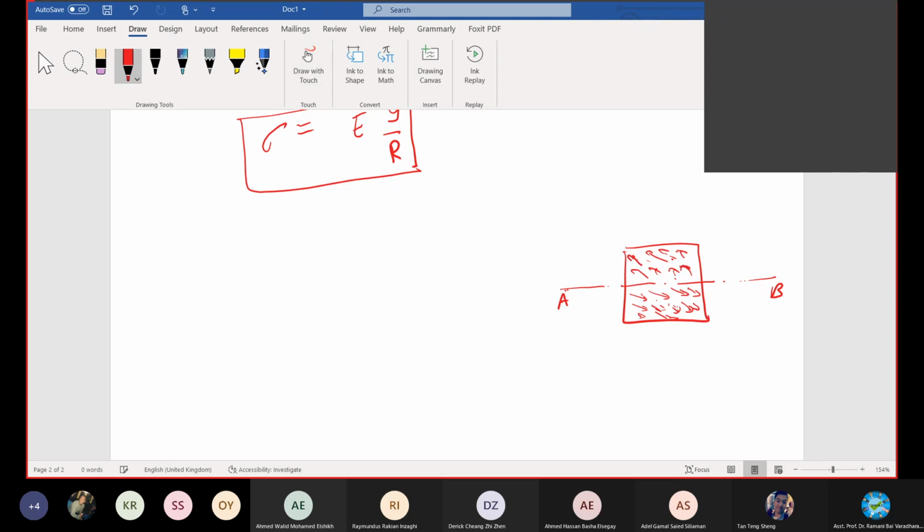One can notice two types of stresses. That's why you have the hogging type, which is compression on top and tension at the bottom. Put together, we can say this is acted upon by a moment called M. Okay, net result or overall result, right? You know that the member is subjected to compression here and tension here. That's what I'm plotting here. On the top member, right above the neutral axis, the member was subjected to inward stress. Below the neutral axis, the member was subjected to outward stress. Overall, we can say it is subjected to a moment M.